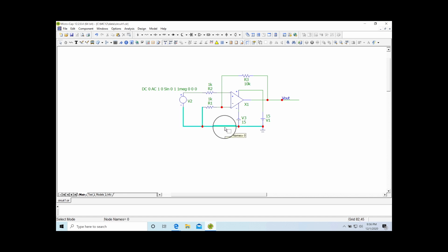It doesn't really look good, and on a simple circuit when you only have one return, that's fine. But on power supplies, a lot of times we have multiple returns, and then you have to decide which return each ground goes to. A ground symbol is a global signal, so it's globally connected to anything that looks like that, and it's meant to make things cleaner.